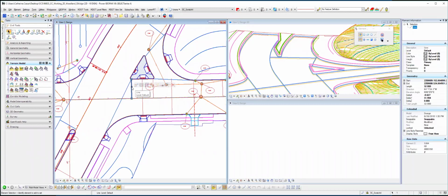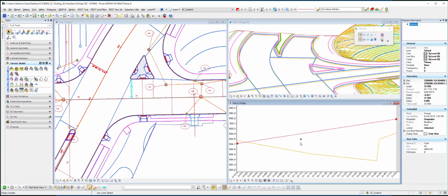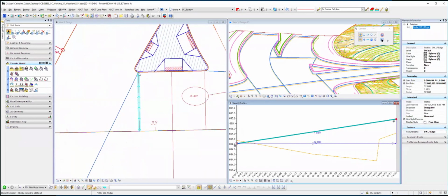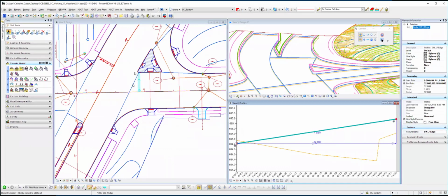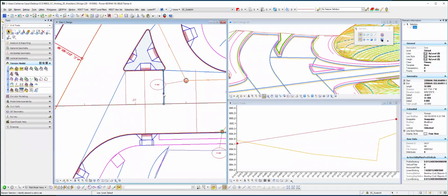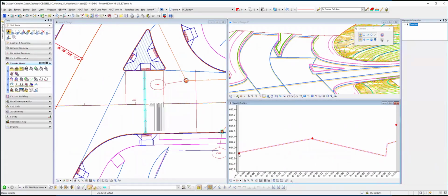So in this case, these were dumb lines, and I wanted to make sure that I was warping this pavement coming through. I started here knowing that this was in a superelevation, and I wanted to tie into that. So this point here is the point over on this edge, which is my edge coming through for that supered section. So I knew I was at 1.48%. This is, I think, a different line. This is for checking these sidewalk ramp conditions. This is what's happening here, and this is just for me to see what's happening to the pavement.